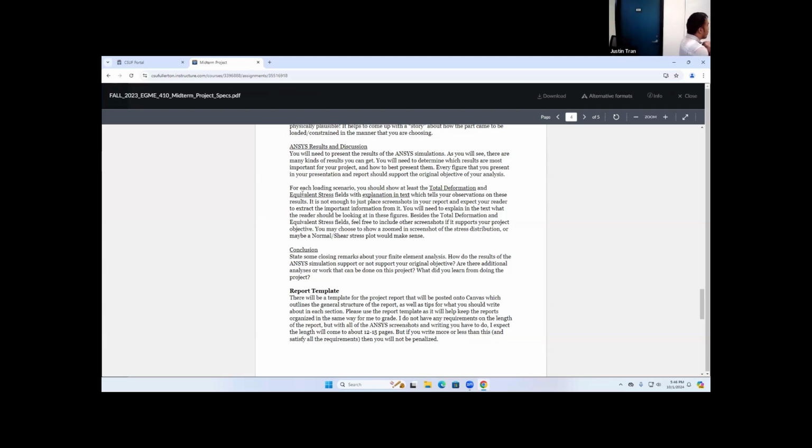One thing that's new in the report, that I haven't been the strictest with in the activities, is that I want you to explain your results to me in the text itself. It's not enough just to run the simulation and give me the figures for total deformation and stress. I want you to explain to me what I should be looking at in your results. So tell me, what is the maximum deformation? Where does it occur? Where is the maximum stress? Where does it occur? Does the maximum stress exceed the yield strength?